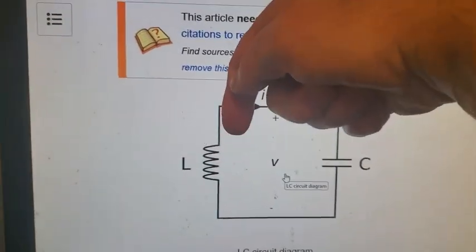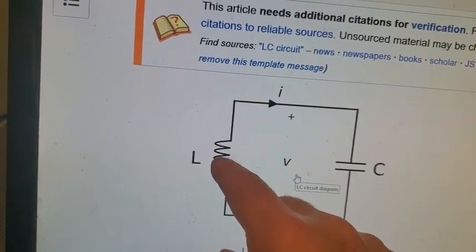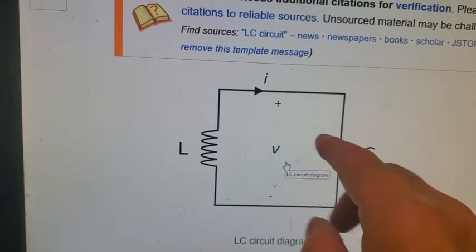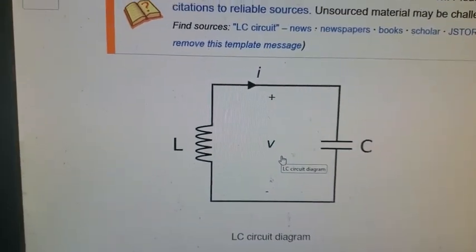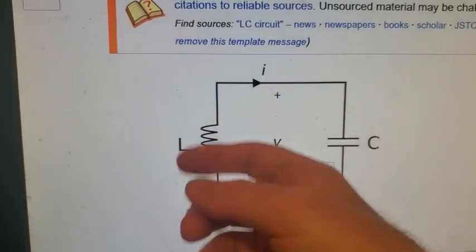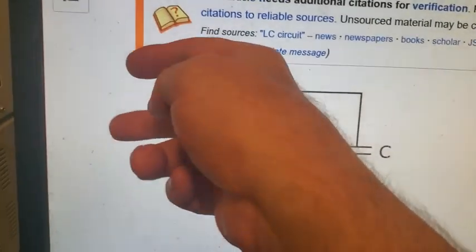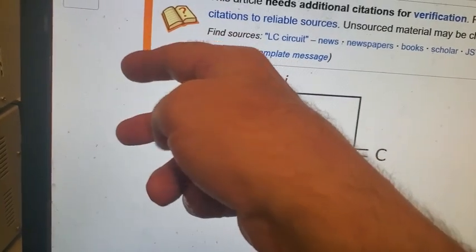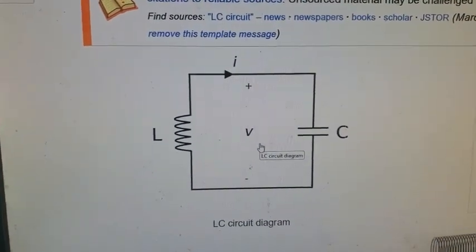Now you break this line and you make a line out to here. And now it's shooting out here the same as if it would be shooting back here, and you don't have to worry about the diode. The diode, you don't need it. If you set it up that way, you break the line here, and at the same time that you break that one, you make a line to another cap. So that's going to have to be done, synchronous rectification.